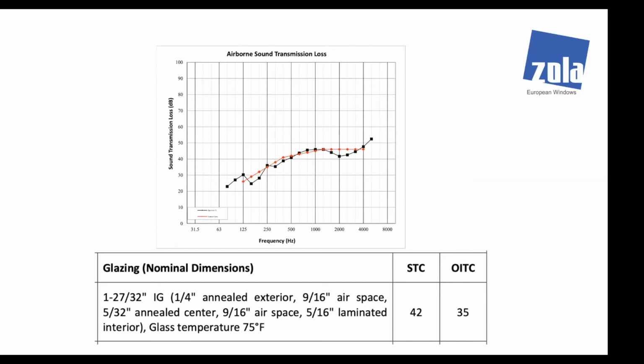If you look at it and think, hey, it's only going to stop 35 decibels in the higher frequency, that's not actually true. It's actually up in the mid 40s for those types of things. And it actually keeps going up and up. In fact, if you look at the 4,500, it's actually above 50. So the single number OITC does not always represent the best glass for your situation.